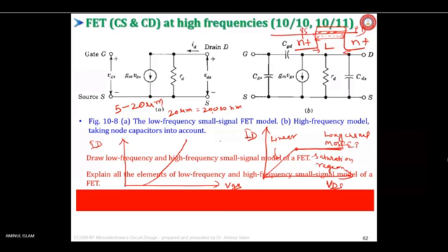Earlier this length was 20,000 nanometer. Now it is less than 20 nanometer. Because of this, the characteristic has changed. Now it is like this. With VDS, current is increasing. This is not a desirable thing, but it is happening. In saturation also, current increases.